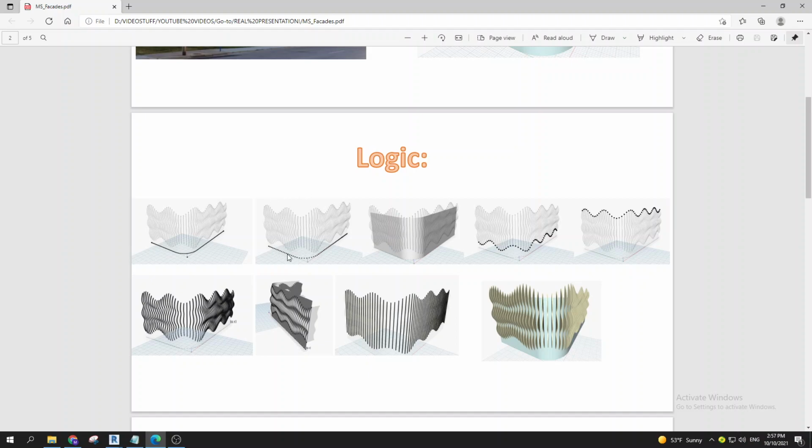The next challenge is to actually create this shape, right? As you can see here at this step, I created that curve, and I can use the curve point at parameter node to help us have some points along our curve. So along our curve, we have some set amount of points. You can create curve.pointAtParameter and set how many points you would like to have there, from 0 to 1 divided by some number. You can have 10 points, 20 points, 30 points, doesn't matter. So you have the points.